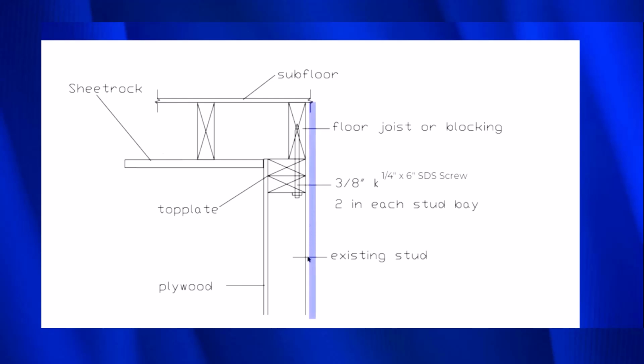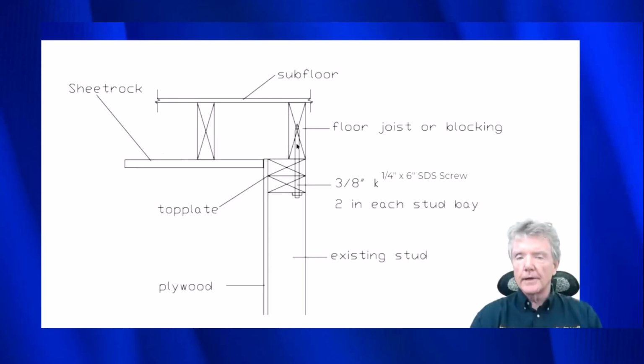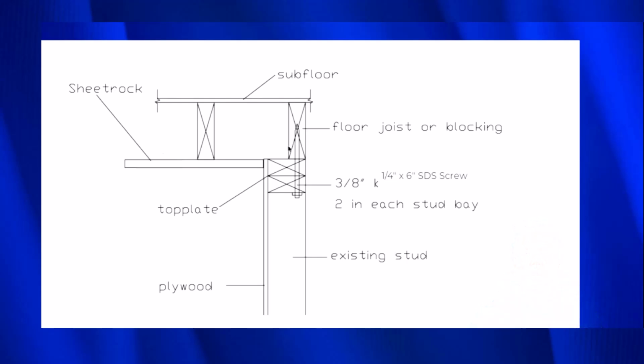And in order for the siding to fit, the joist must be right on the edge of the upper top plate and the lower top plate. So when we drive a lag screw through these top plates, and we get it right in the center, which is what's required by the manufacturer of the screw, it has a lot of capacity. It can resist 400 pounds per lag screw, and it allows us to do this when there's sheetrock. So I'd like for you to see this right here.